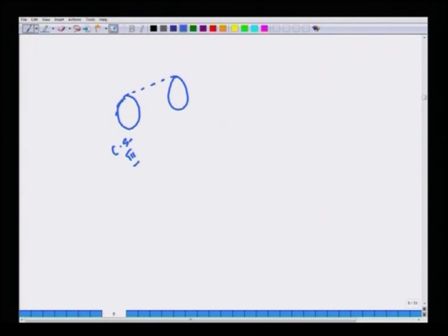So, this is a patch on the surface of the control volume, or control mass. This patch is denoted by a vector unit outward normal dA, this is inside, this is outside, and in general the fluid velocity on that patch will not be in the same direction as dA, in fact it will be at a direction theta.